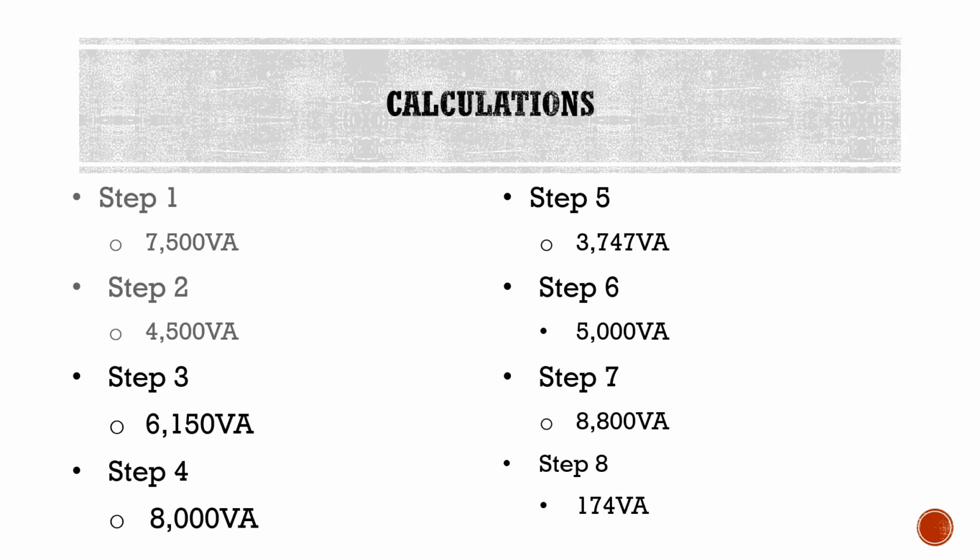What you have to keep in mind, and what I see people get confused on a lot, is that we already used 100% of that motor back in step number 5 for our fixed in place appliance load. So for step number 8, all we technically need is the additional 25%. In other words, if you add the load that we had in step number 5 for that disposal and the load that we added in step number 8 for the disposal together, you end up with a total of 125% of the load.